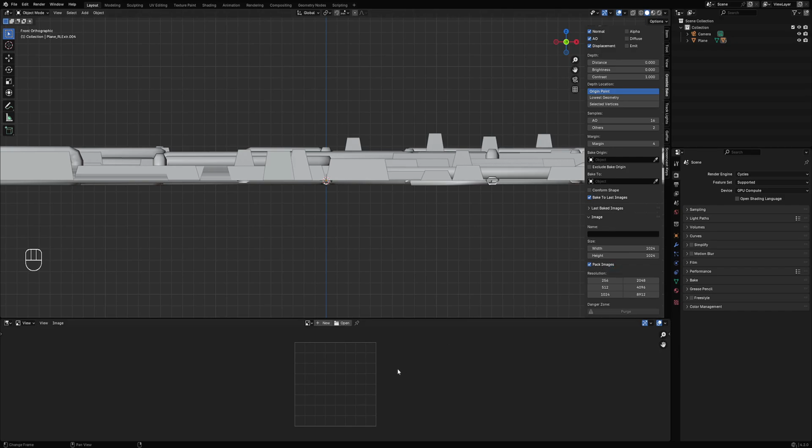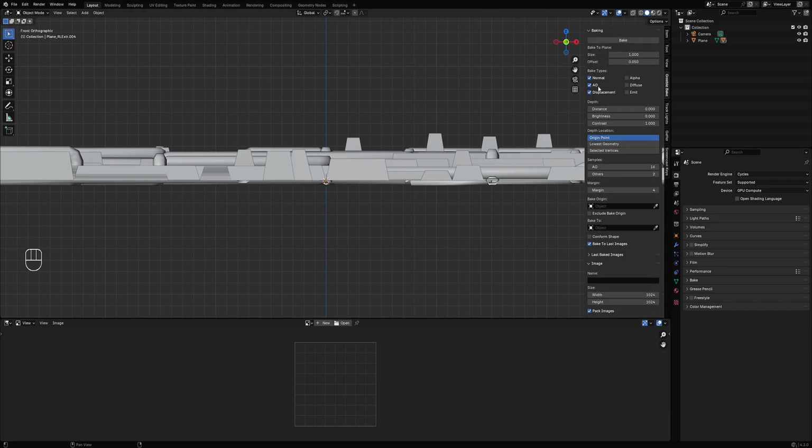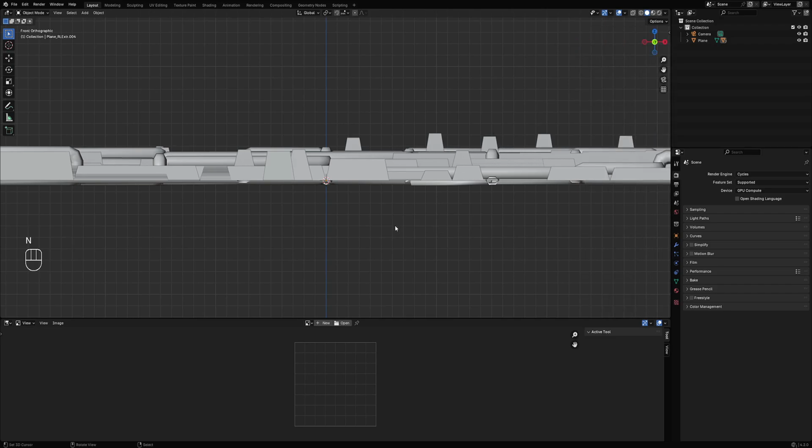You can then choose to save them, and because of the suffixes, you can save them into a single folder and then use Node Wrangler to assign them to a shader, and Node Wrangler will automatically place them correctly as the displacement and as the normal. It doesn't have anything for AO, but you can manually just place it, and also the diffuse and the emit. So those underscore suffixes will come in handy for Node Wrangler.